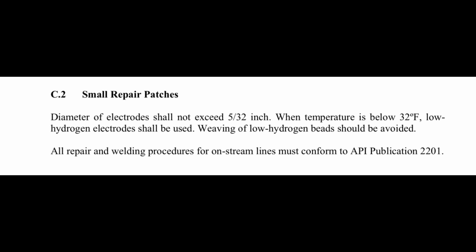The next one, small patch repair patches. Diameter of electrode shall not exceed 5/32. These are all instructions related to your repair. Okay, just go through this.